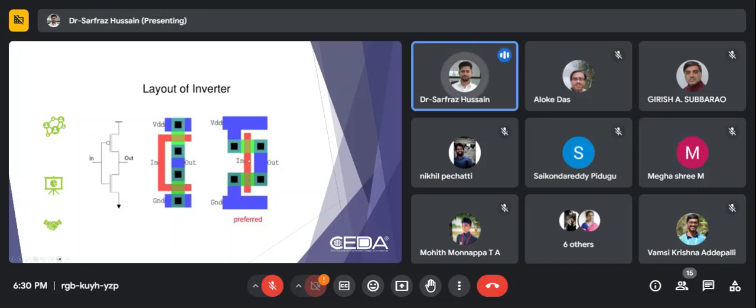So you see the polysilicon. The size of the polysilicon is small here, whereas in the first figure the polysilicon is larger, right? This one is large in size compared to figure 2. We don't want a larger polysilicon, because if we have large polysilicon, then we'll have more parasitics. So in order to reduce the parasitics, we should have small polysilicon connections, or polysilicon wires, basically. That is why this particular figure, part 2, is preferred.